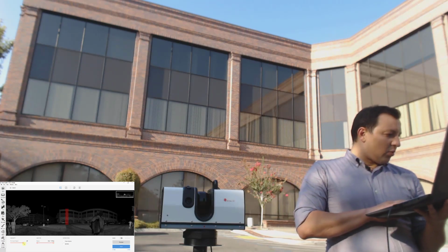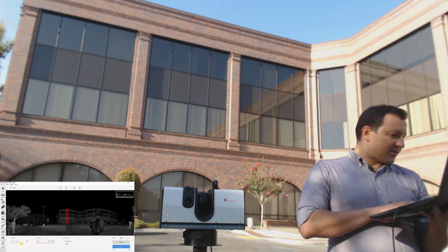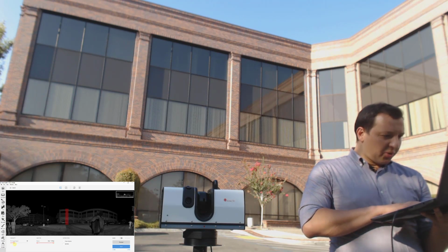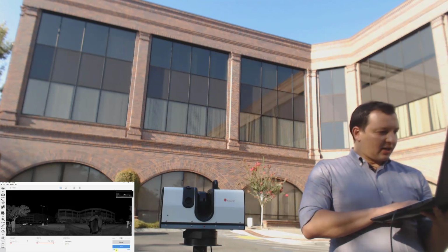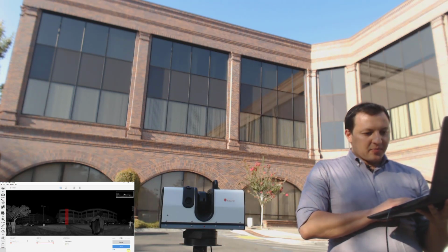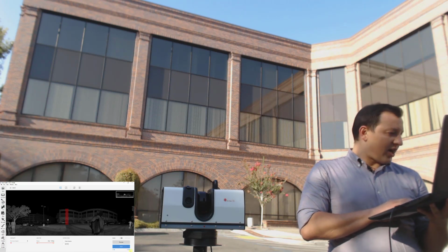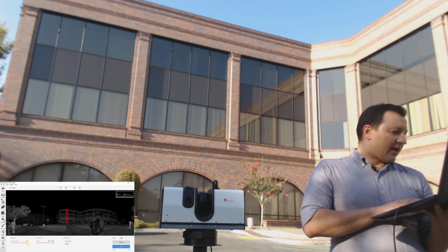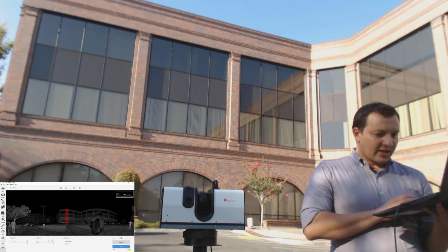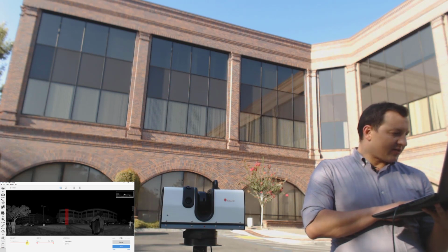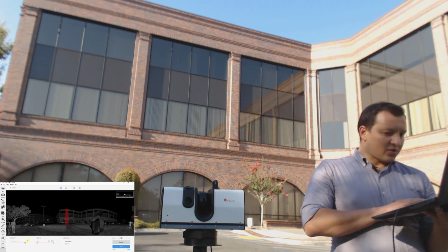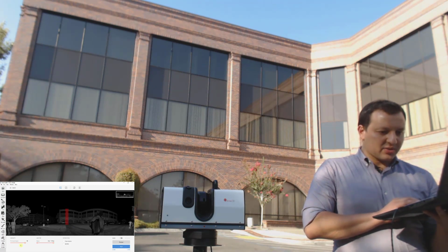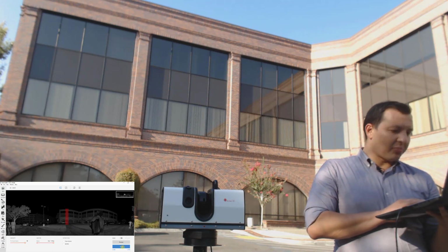And here we can play with the points per degree, with the point density. If we increase or decrease the point density, you will see that the amount of time that the software tells us the scan is going to take is changing. At the lowest level, it's going to take us less than a minute. At the higher densities, it's going to take us about 2 minutes. Let's split that in the middle and make it just 1 minute. So this scan should take us about a minute with this point density, 70 points per degree.